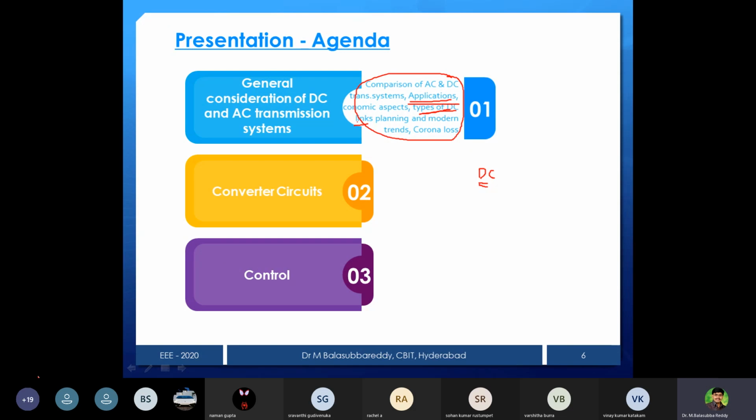Here a lot of equipment will be there, because protection will also be required. DC filters are required and tuned AC filters are also required. Like that there will be reactors. And then on the input side, we need to use transformers, because the 12 pulse converter is generally used in HVDC transmission. So there are 2 six pulse converters connected in series, therefore we have to use a transformer connection also. Star star connection and star delta connection will be used. For the first 6 pulse converter star star will be used, and for the second one star delta.